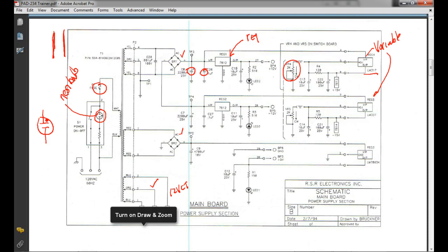So neon bulbs just work on the same principle. These guys, we don't call them neon bulbs, but they use mercury vapor up there. And we shoot electrons through mercury vapor, and they glow, right? The gas is what's actually glowing. By the way, you have to use these things with a resistor. They have a high resistance, but as soon as they start gassing or emitting light, their resistance drops down a lot. So you need to protect these things with a resistor. We wouldn't put it directly across the 120 volts, right? You understand? Because as soon as you turn it on, it'll bomb.